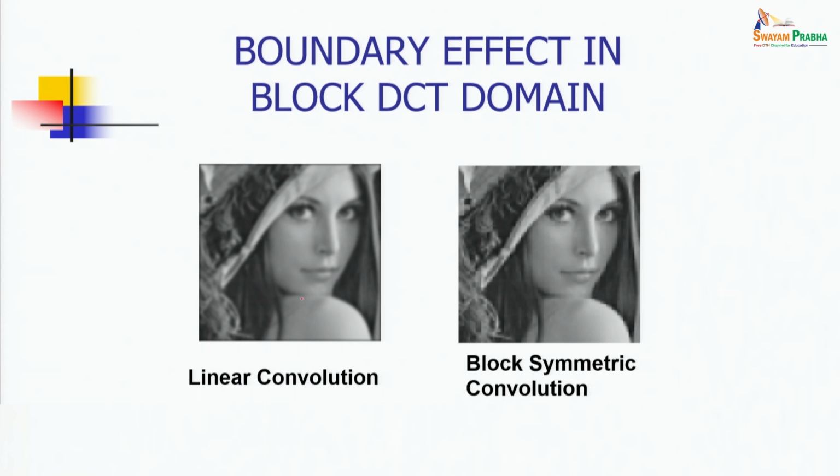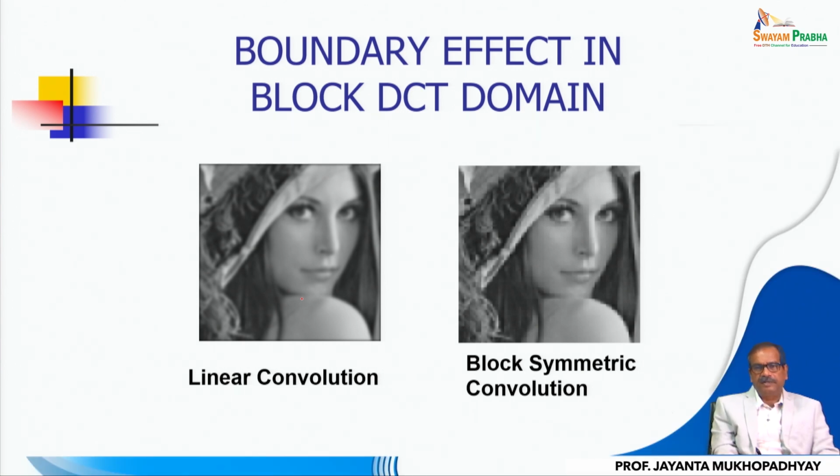We have considered large Gaussian filters so that edge effects are negligible, and then that mask is convolved everywhere. So it's a spatial domain operation. So this is the linearly convolved image. Now for the same filter response, of course, it has to be truncated to n+1 samples, as you understand now.